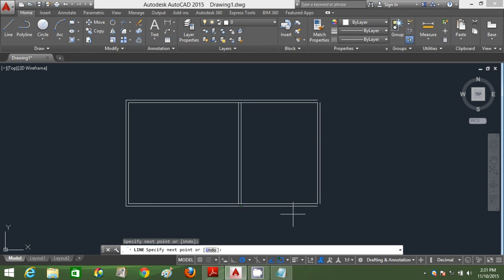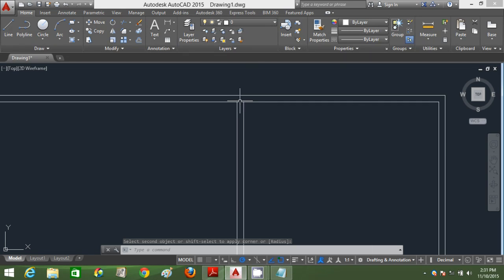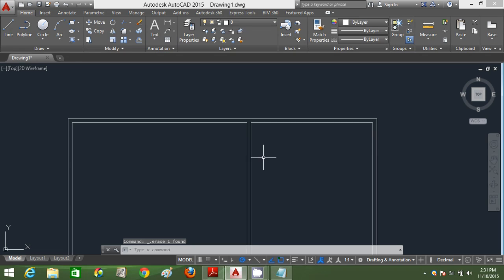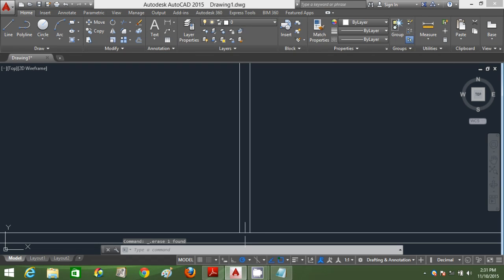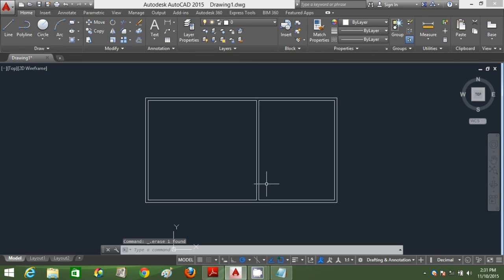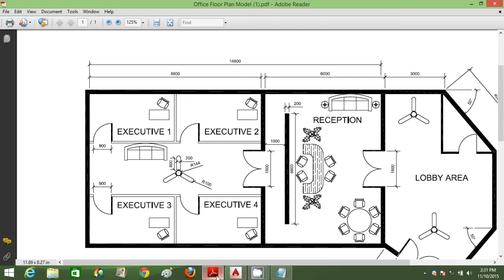Alright, click fillet again and join these two lines. Fillet with radius 0. Okay, click fillet without defining any settings of a radius, and just click both lines. So this particular portion, I'm going to select and delete it. Alright, I'm going to select and delete those two reference lines there. I'm going to look back to the floor plan again.